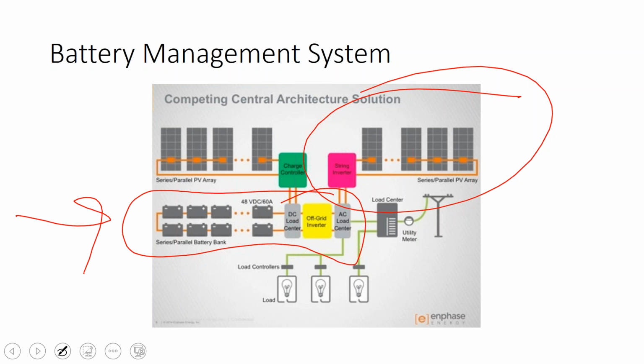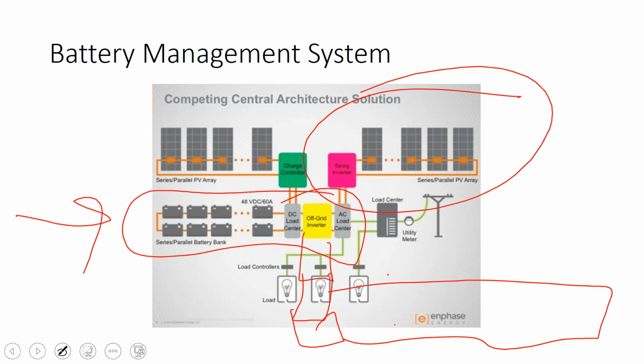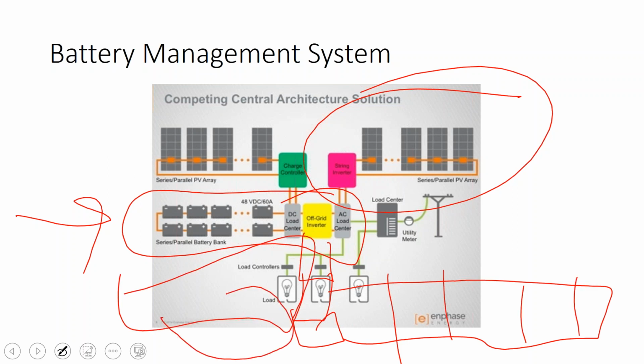The only thing is the manufacturers say if you're doubling or tripling or quadrupling, or putting in 10 battery inverters because you want to have a giant battery bank, stay within the same line. So don't have multiple battery inverters from multiple manufacturers on the same system. Just stick to one product line at that point.